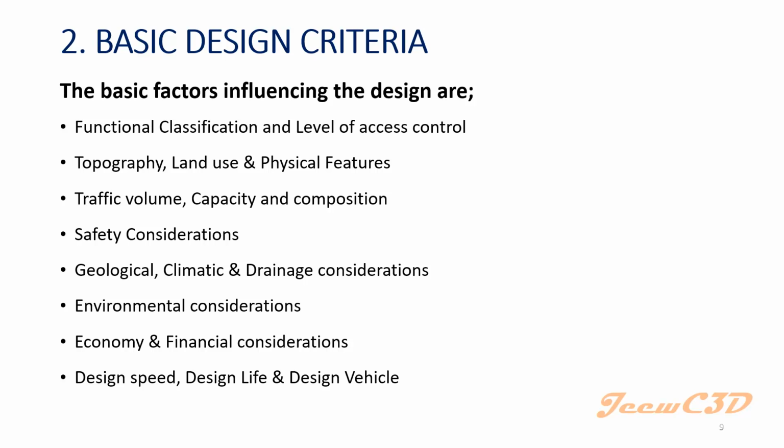Design life, that means how much is the life of the road before doing any rehabilitation or before doing a modification to the road. What is the design life? That means after the design life you have to re-modify your road. That means you may have to increase the road width, you may have to do a new layer on the road, or we call it overlay. That kind of things may be there, but within the design life, the road should provide its safety and comfort driving to the road users within that time period.